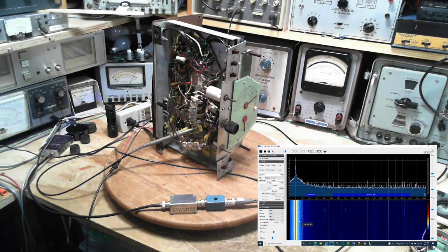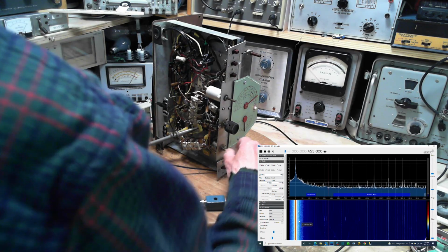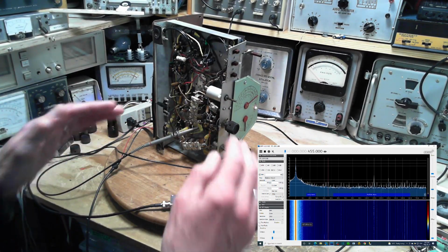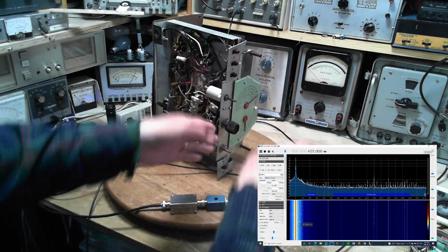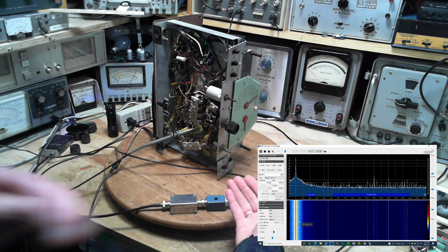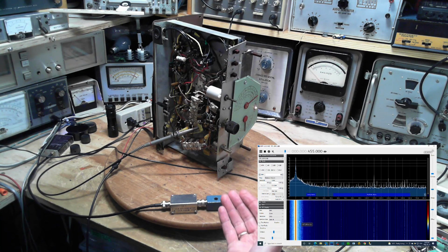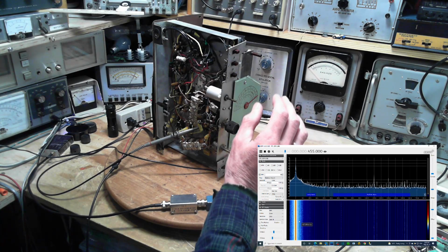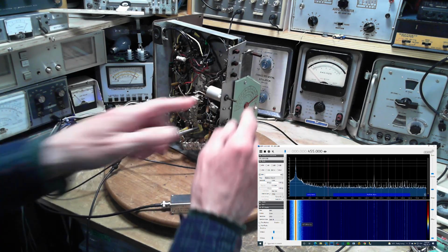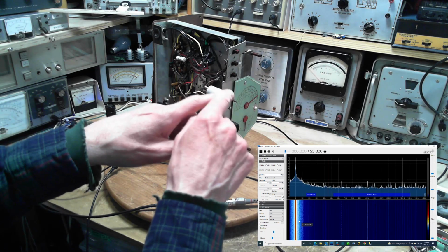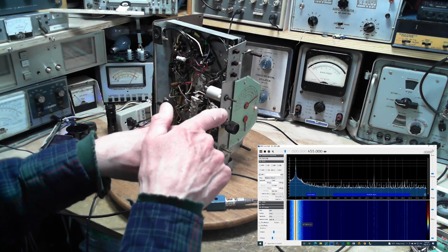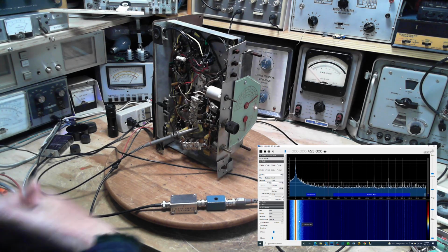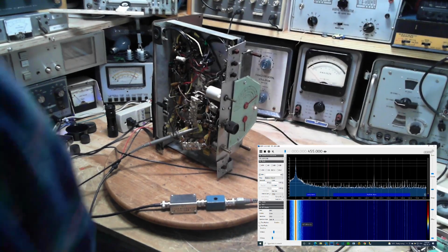Now, I guess something to realize here is we're looking at the output of the mixer tube before it goes through the IF tuned circuits. On the far side of the IF tuned circuits, or on the output side of it, you're only seeing through a little portal, 455. And if we were looking there with the SDR, we would just see action at 455. But because we're looking at the start of the IF, we're seeing everything that's coming out of the mixer tube spread right across the whole bandwidth, and maybe beyond what's on the screen.